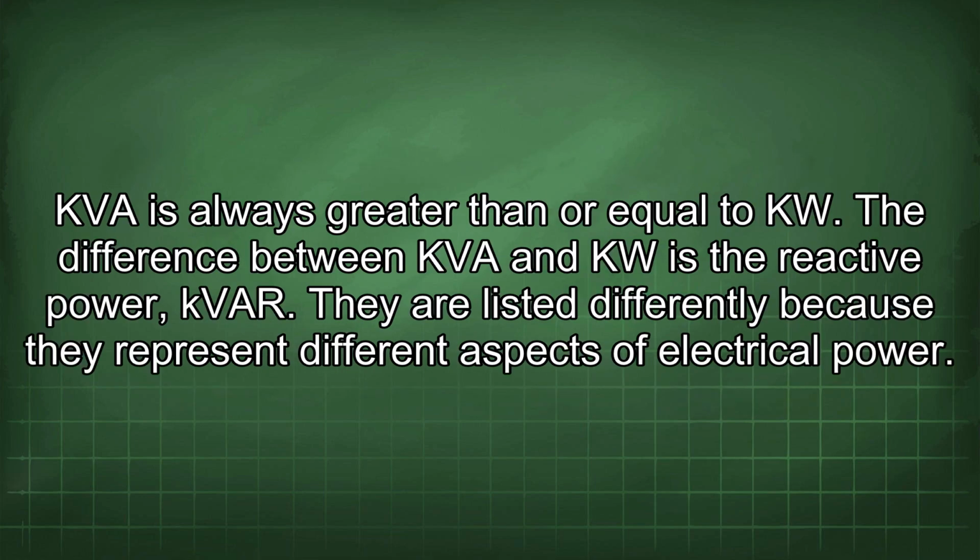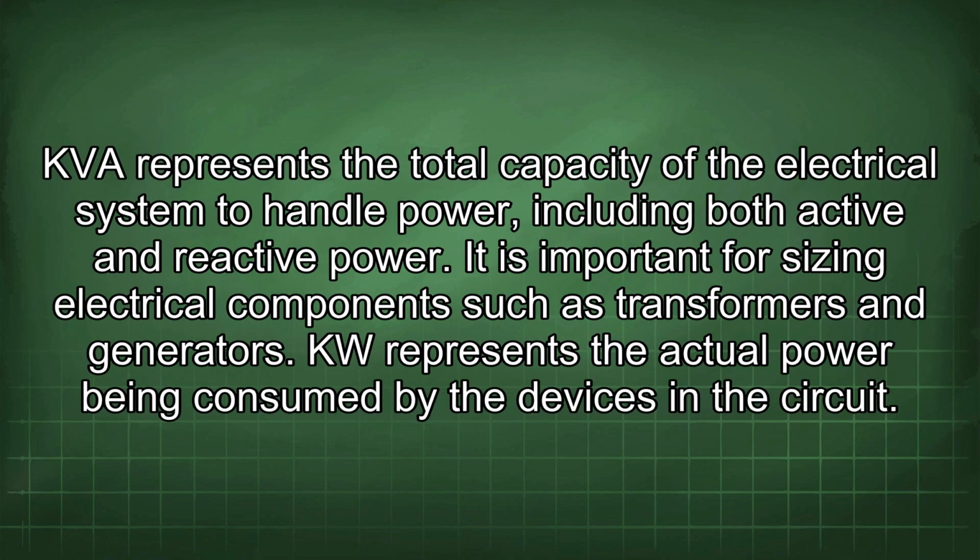KVA is always greater than or equal to KW. The difference between KVA and KW is the reactive power, kVAR. They are listed differently because they represent different aspects of electrical power. KVA represents the total capacity of the electrical system to handle power, including both active and reactive power. It is important for sizing electrical components such as transformers and generators.